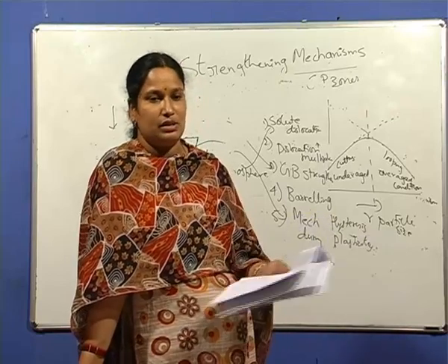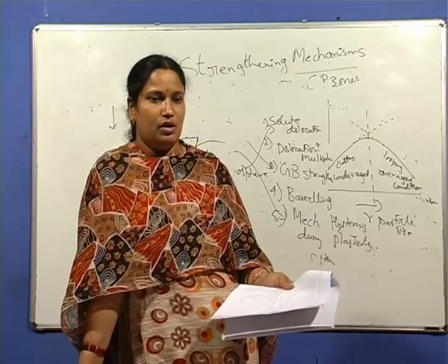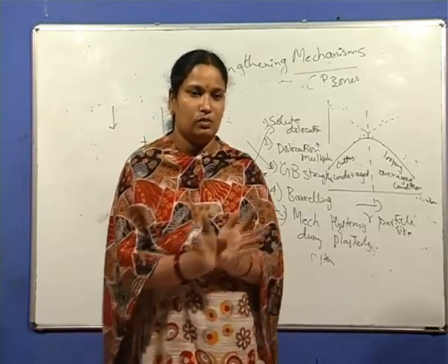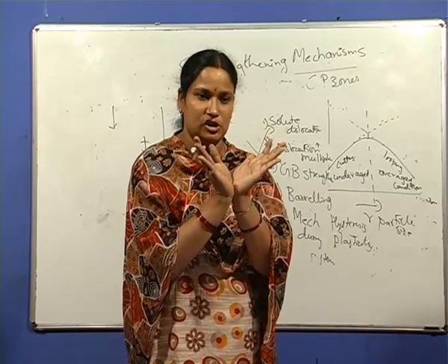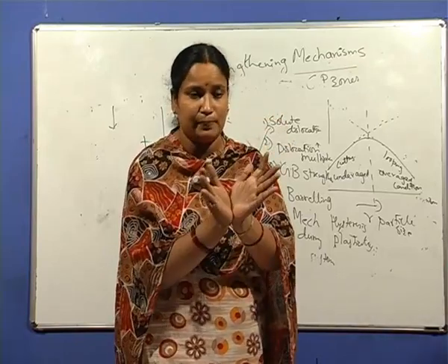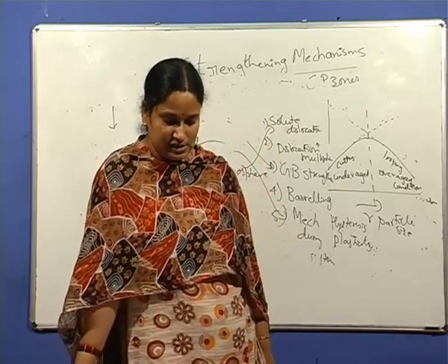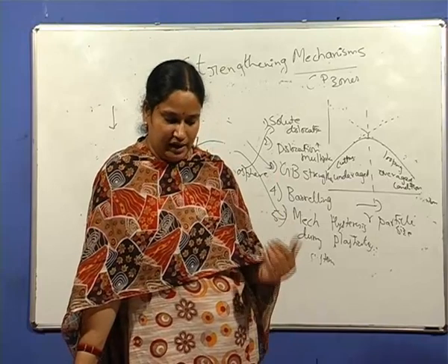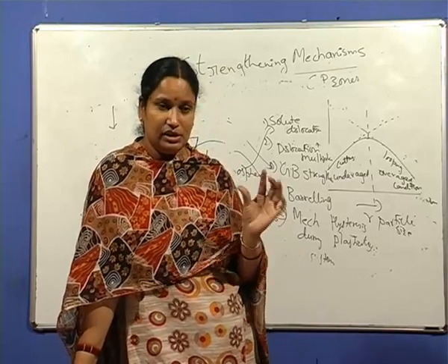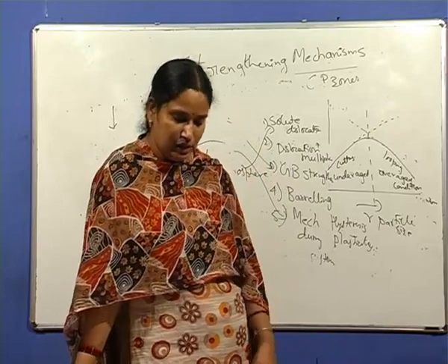Just in today's lecture, we have discussed the stacking fault energy. When stacking fault energy is low, the faulted region is wider and it is difficult to cross slip. If it is difficult to cross slip, the strain hardening is higher. Thereby, the answer for this is A: high stacking fault energy, it is easy to cross slip and work hardening is low.